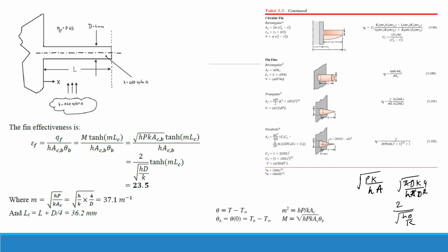Then the other thing we studied was, in order to increase the heat exchange rate through any given system, you can use these extended surfaces, also called fins. Then we saw the derivation of the heat transfer through the fins in brief, and that gives us some equations. So we can straight away use those equations in order to find the temperature profile across the fin as well as the heat transfer rate. And then we studied the two concepts of fin effectiveness and fin efficiency.